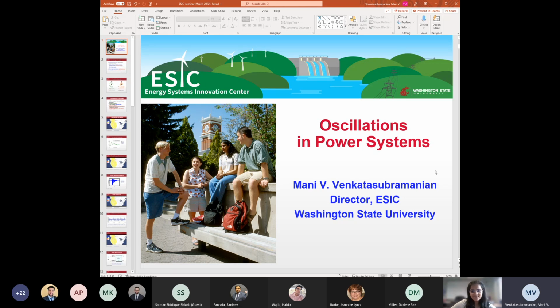Yeah, that was a major event, and in fact, it led to many modifications in the operation and planning of the Western power system. One thing we realized, the tie line limits were too high for acceptable transfer from north to south. So the whole process of how we determine the tie line limits was revamped after the 96 event. And again, we can do post-mortem studies or even offline studies in planning type analysis if we have good models. So a lot of emphasis on cleaning up the models, doing periodic testing. So that has been a major effort.